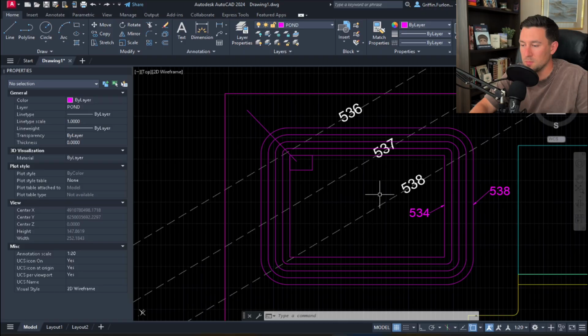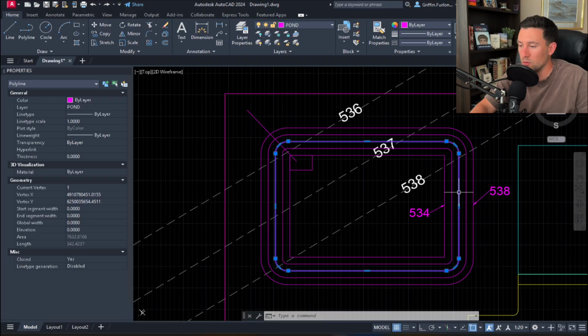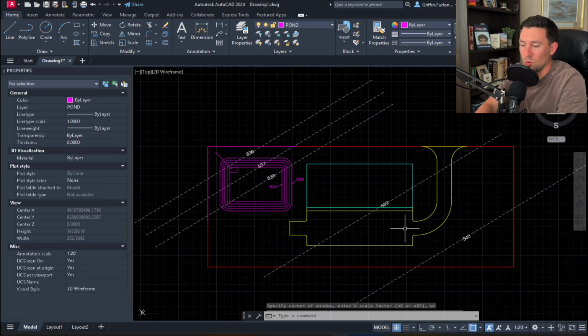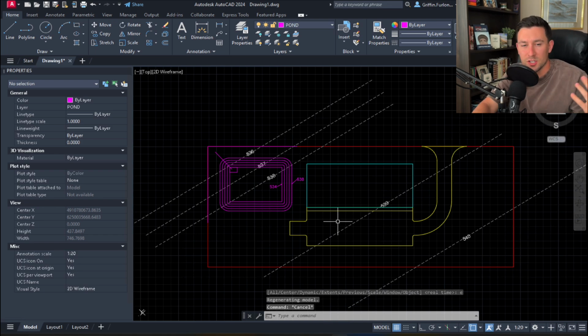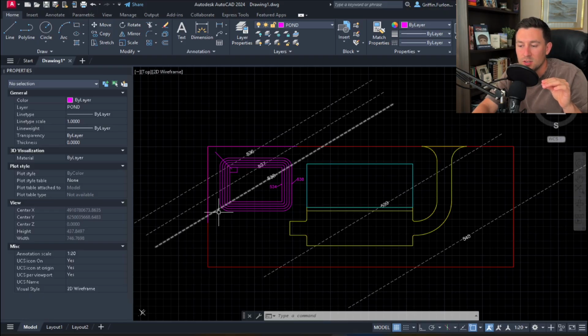So just to put that into perspective here, our design high water is staging up to this contour right there, which is pretty good. Considering that's the case, technically this pond is a bit oversized here. So I could either not dig so deep, I could decrease the size, I could lower the top of bank. I mean, there's so many things that we could do. And that's the beauty of stormwater: you have a million decisions, but as long as you know the key factors, which is sizing your weir and then sizing the volume of the pond, everything after that can just get really creative. I've seen a lot of projects use underground chambers when space is limited. There's a million ways to skin this cat.